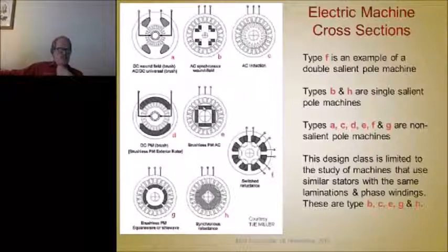And so you get torque from the magnets, but you have some little steel poles in between the magnet poles here, and you can vary how big those are. You can adjust the reluctance torque component you get from those soft iron poles that are between the magnets.